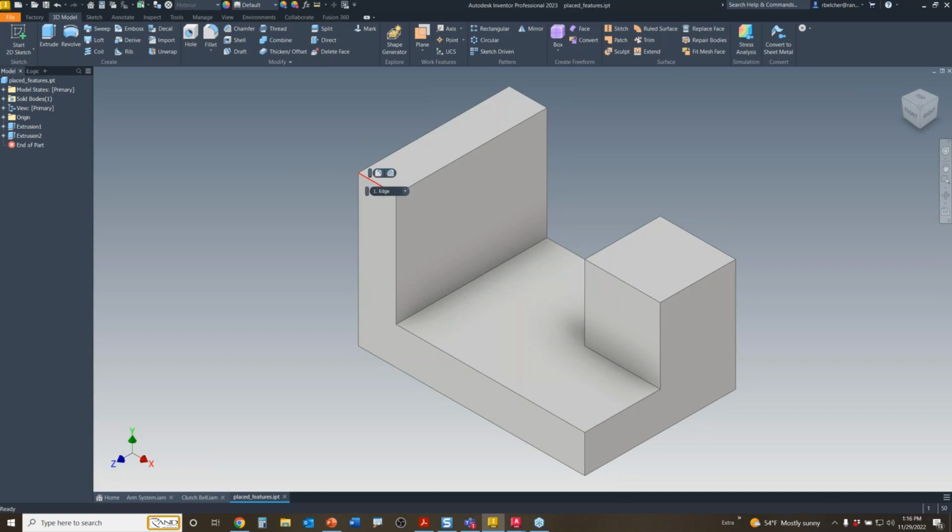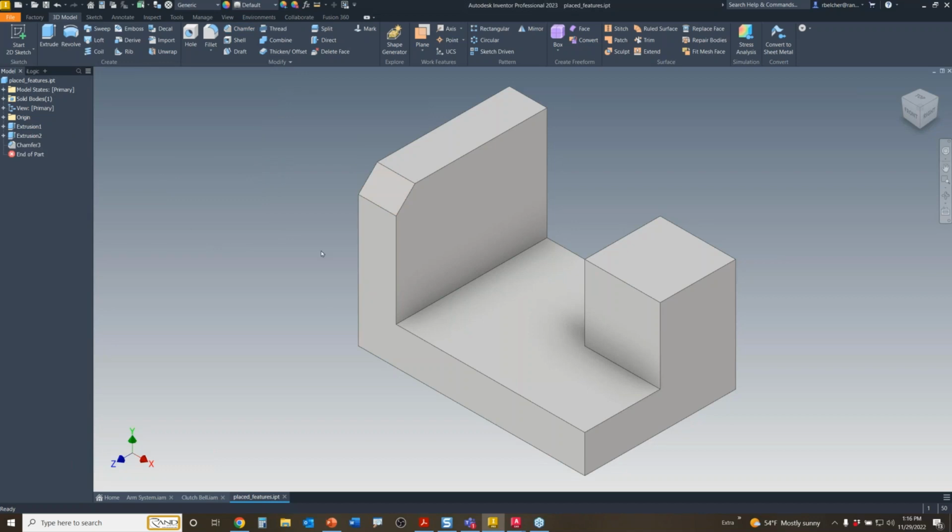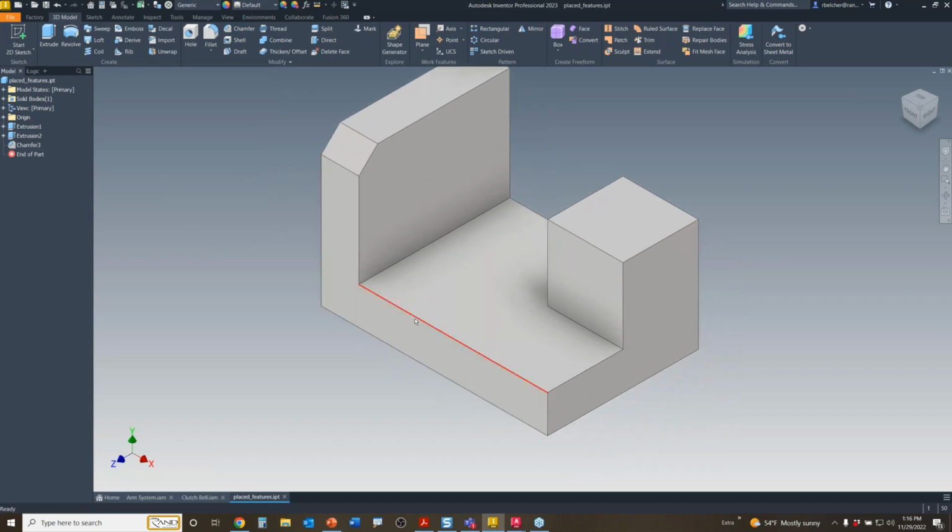When you select the edge, the selection is context sensitive and will give you the ability to fillet and chamfer right here in this little mini toolbar. So I can click chamfer, and then through the incremental values, I can drag the little arrow until it stops at the desired half-inch chamfer. I can hit enter. There you go. I didn't have to mess with the dialog at all.